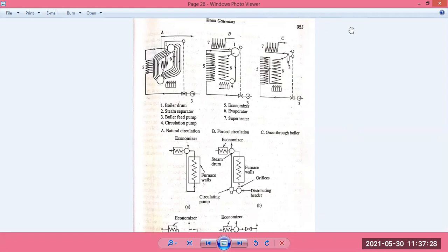The heat transfer to the water tubes around the walls is mostly by radiation from the fuel flame, and less by convection from the flue gases. What is the source of heat, and how is the heat transferred to the wall? Mostly by radiation, and less by conduction and convection, which means the flue gases do not directly come in contact with the walls, but the heat energy produced by the flue gases is transferred to the wall by radiation.